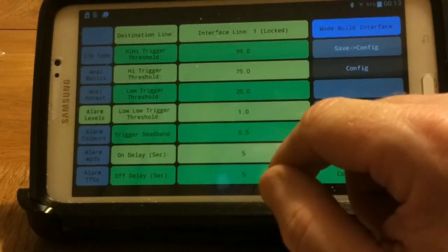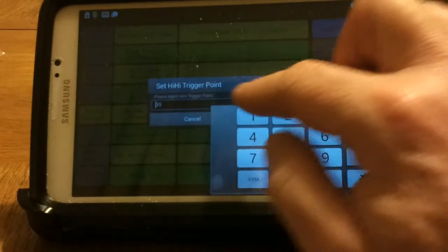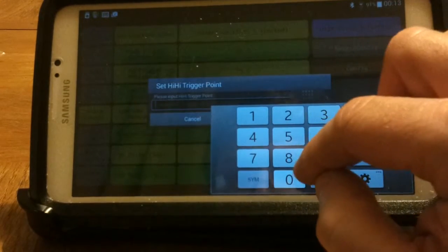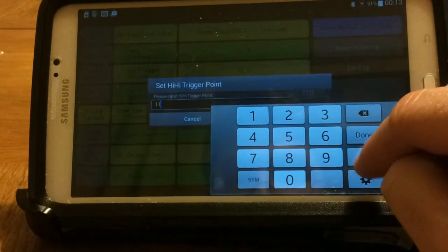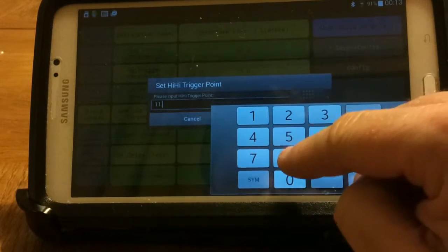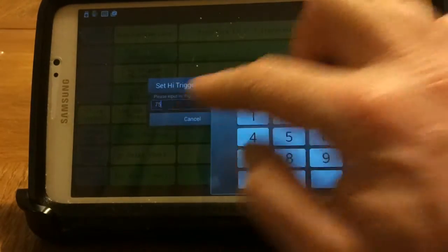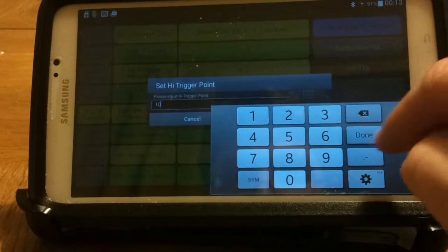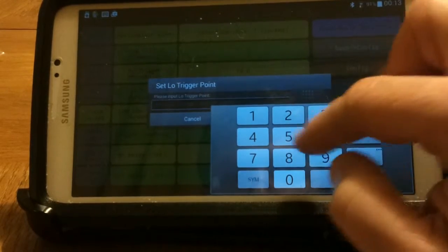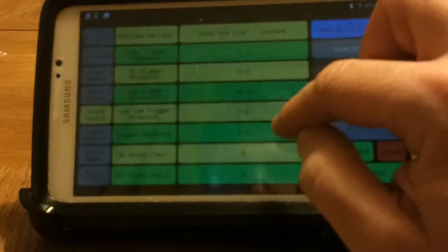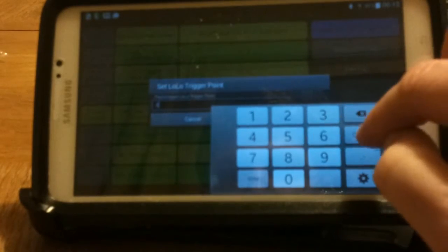Next, we have to set our thresholds up, so I'll have the high trigger point on my battery alarm trigger when it passes below 11.2 volts, and then again I'll have another one at 10 volts, and then another at 8, and then another at, although your battery would be very badly broken at this point, 6 volts.